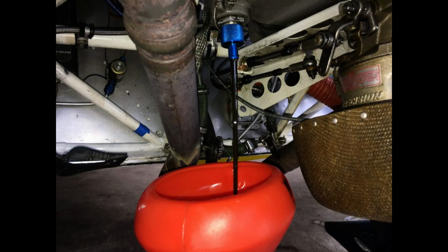Oil. The empty weight for aircraft certificated under the Civilian Air Regulations, CAR Part 3 does not include the engine lubricating oil. The oil must either be drained before the aircraft is weighed, or its weight must be subtracted from the scale readings to determine the empty weight.